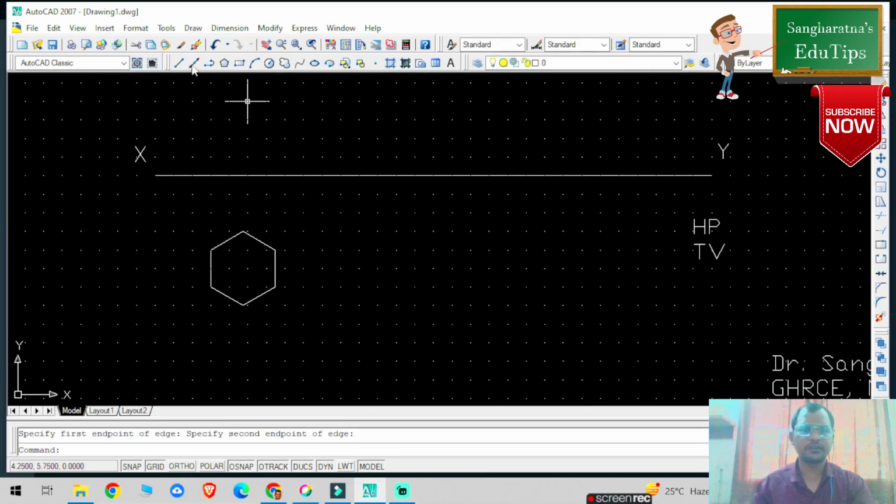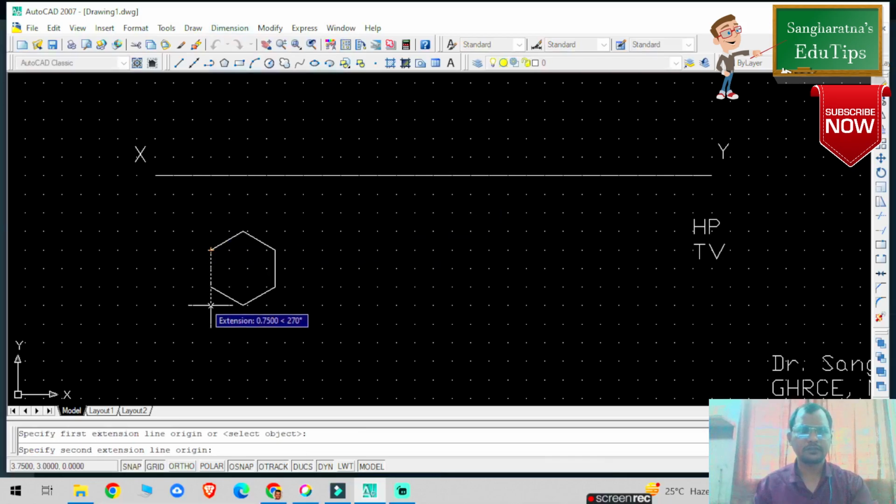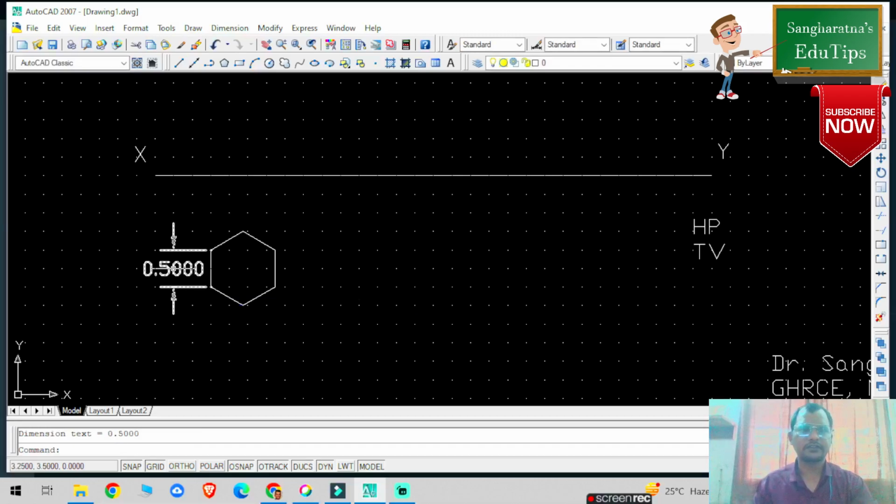So just zoom in. Now what you can do is give the dimensions. Go to dimensions, select a line, and click this particular point. You can check this is the 50 mm hexagon. So convert it into cyan color.